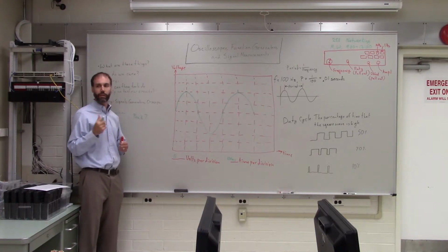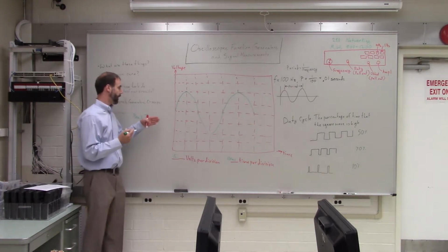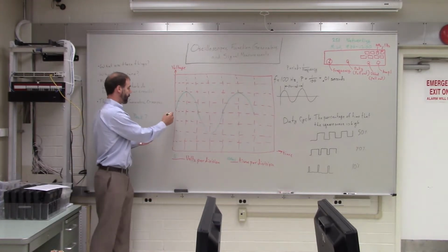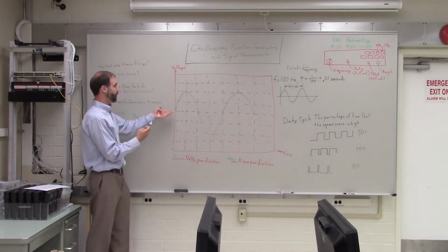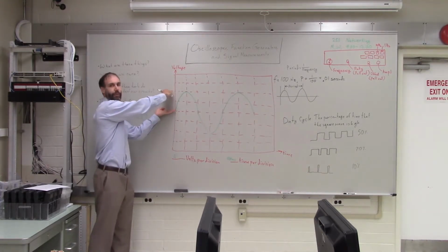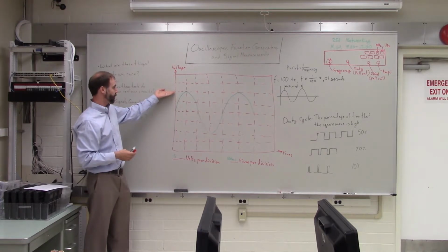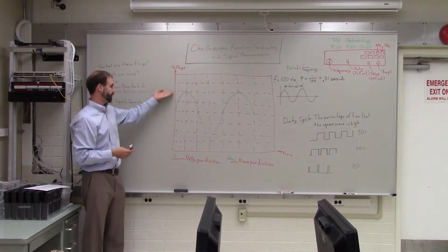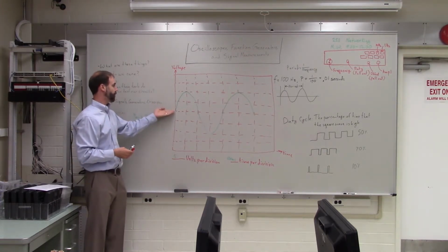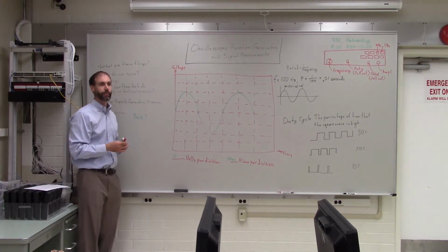peak amplitude for this signal? Just peak. Yeah. Yeah, exactly. It's 10 volts. And we can tell that because, remember, the peak amplitude is the distance from the middle to the top of the wave. We see that there's 2 divisions from the middle to the top, and there's 5 volts per division. So that's a total of 10 volts from the middle to the top.